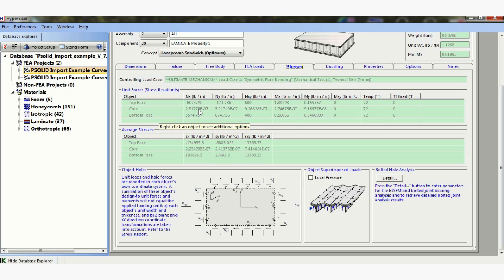Stress. Well, what's ironic really is these aren't stresses. These are loads. So maybe I think these should go in free body, but I don't know. I mean, this is what we use in a free body. The standard stress gauge back in the old days only used Patran to go and find these internal loads. Patran was a loads tool. Patran's never been a stress tool. And what we had to go and find is our NX, NY, and NXY, then go do our analysis. So these are loads, they're not stresses. So I'm not sure why they belong here.